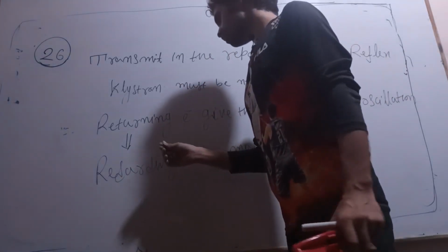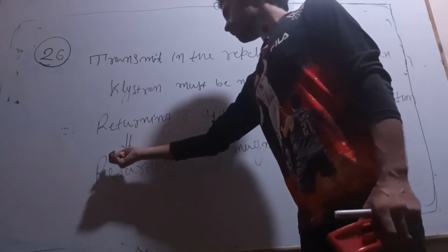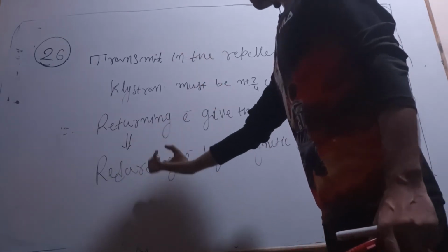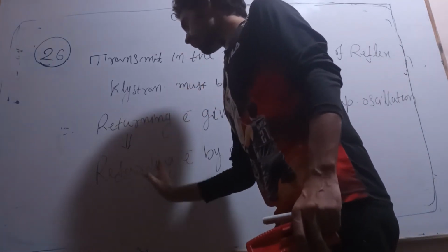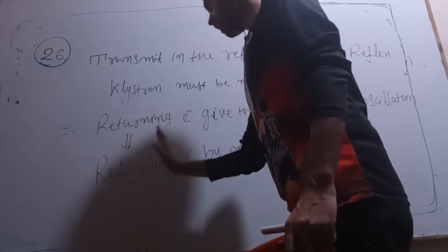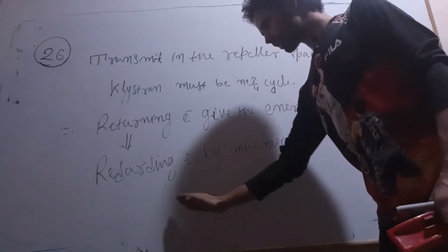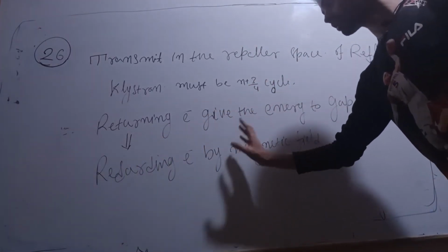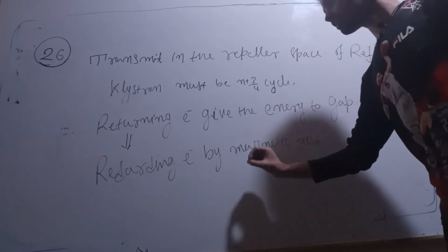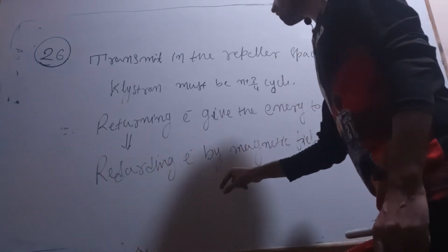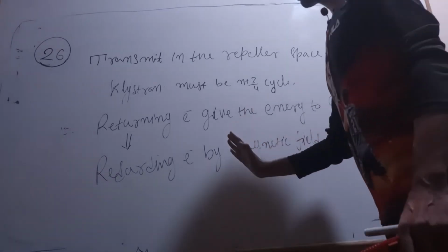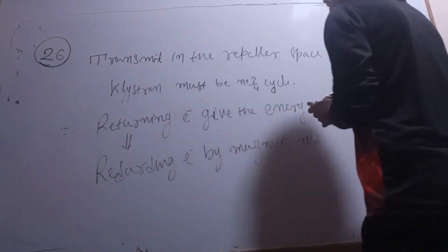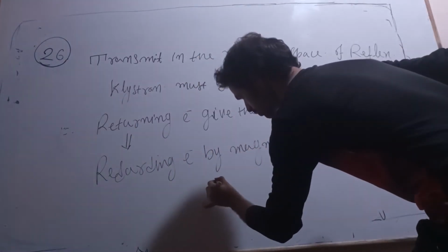In the case of a magnetron, it is a retarding electron which is retarded by the magnetic field. When it is retarding, the electron velocity is decreasing, so the kinetic energy of the electron decreases, and this energy loss gets transferred into the RF signal. And here the transit mode will be n plus 3 by 4.